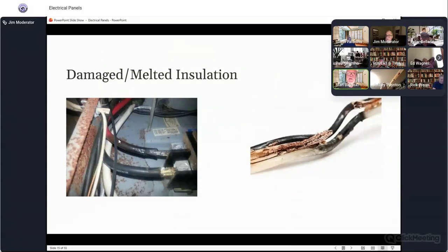And I would put a rush on that in my report because we don't know if that was corrected or not. A lot of times the wires barely get to where they want to go. Somebody might have tightened that lug up or corrected whatever the problem was and couldn't cut the wire back and get it back to the breaker, so they leave it the way it was. Just call it out and say that it needs immediate attention. Well, that's what I would do.